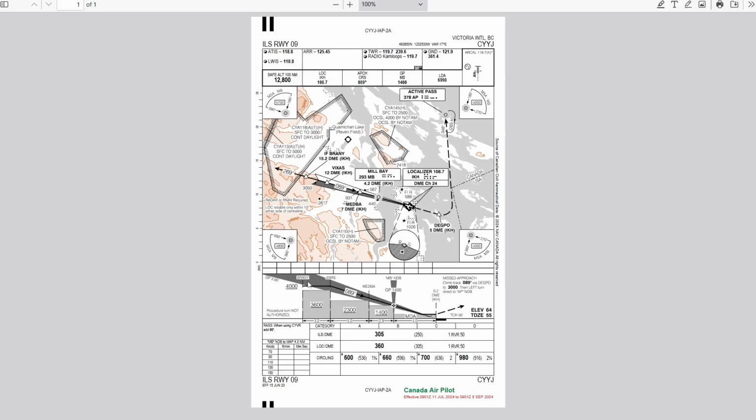So a precision instrument approach will take you down this without you having to calculate and determine and make the airplane go to those certain altitudes. The instrument approach system, if you follow it, will automatically take you down that glide path. In one example, using the older style instruments, you manually fly the airplane following the needles to tell you whether you're left, right, or up and down. On modern systems, it's connected with the autopilot, which will make the plane do it automatically.